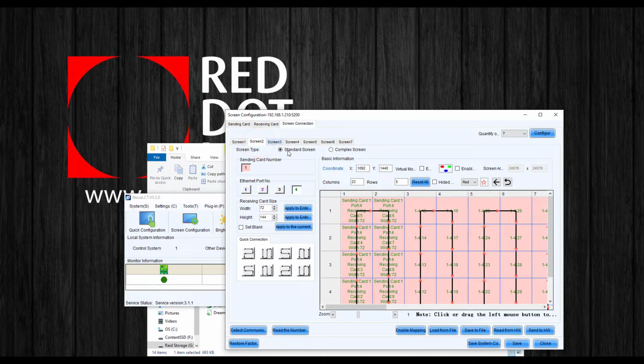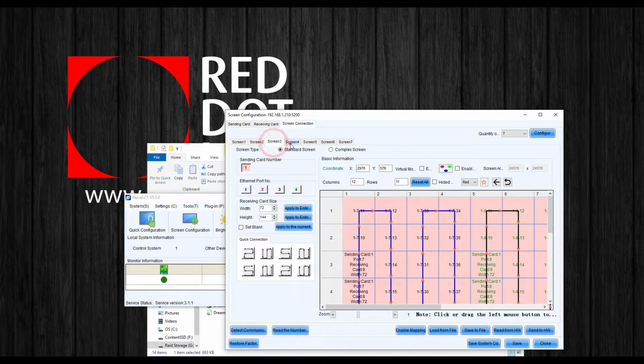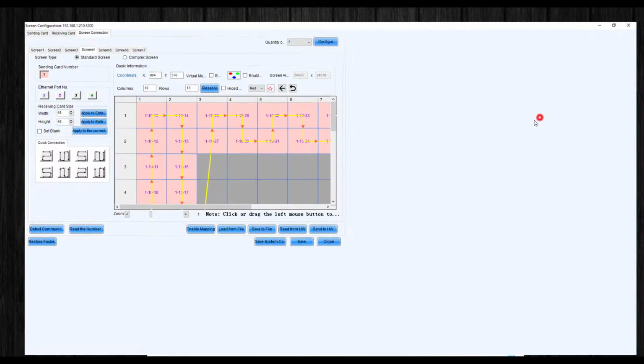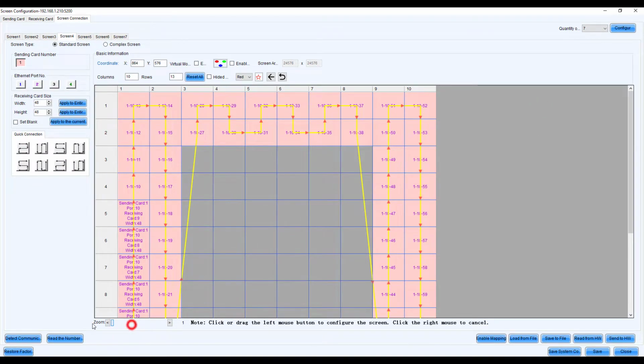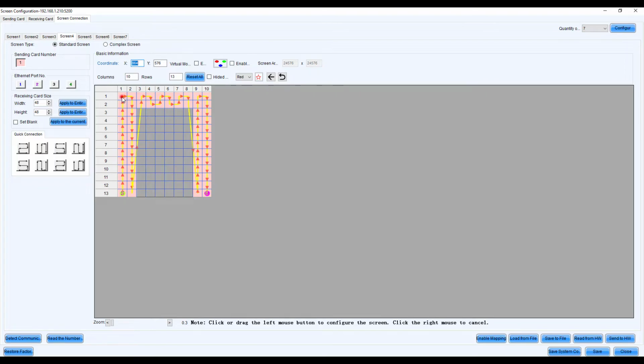And each one of the screens, if you go through it, you'll have the coordinates, exact screen sizes, and the panel count and pixel count for each panel. So right here you can see the border now on one of the Vanish screens. You're gonna have 48 by 48 pixels, and you can see I've added in blanks right here by clicking on set blank. If you don't know how to do that, you must do all the blanks that you're not using. And we've only done a 2 cabinet border all the way around the actual LED screen. And the pixel count is 48 by 48.